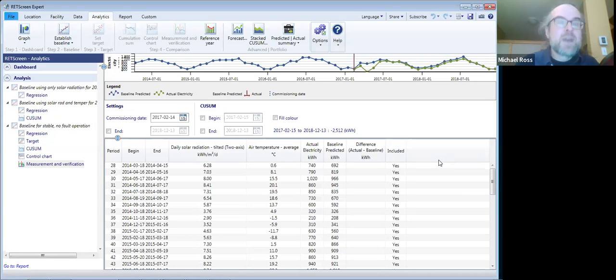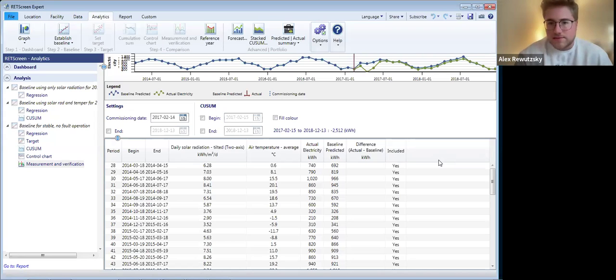It really works quite well with solar photovoltaic projects. It's a bit trickier with wind projects. So don't blindly apply the technique to wind farms. Give it a try, but be aware that you're doing something that's fundamentally more challenging because you're starting with a nonlinear relationship between power and wind speed. Gotcha. Awesome. Thank you. Got another one down here.